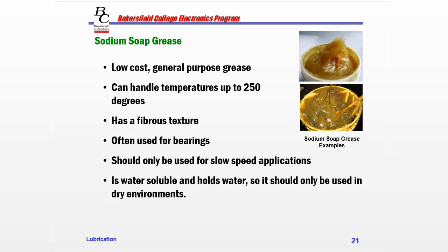So you want to make sure that you're using a lubricant for the intended application, and you wouldn't want to use this sodium grease for wheel bearings for a boat trailer because we put boats in water.